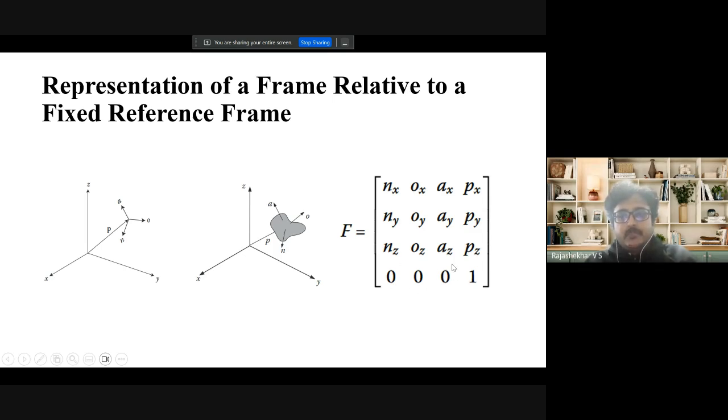But this perspective matrix, that is 000, is 0 because in robotics there is no change happening in the rigid body which the robot is made up of. And this 1 which is at the corner is usually 1 in all the cases, but this can be scaled so that you can actually make a robot which is double or triple the size just by changing the value at the bottom. And if you change this value, the other parameters will carry forward this value as you move further. Is it clear? Okay, thank you, sir.